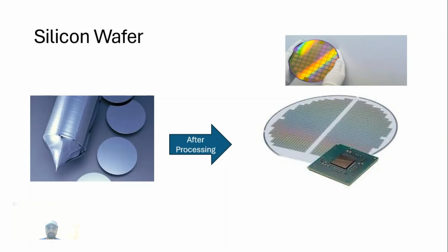Okay. So for the simulation, we're going to take a cross section of it, and we're going to take a small piece out of it. Because the wafer will be 4 inch, 6 inch, or 8 inch in diameter, and for simulations, it's very difficult to simulate such a big domain. So we're going to take a small portion of the cross section. You're not taking the surface. Please understand, you're taking a cross section.